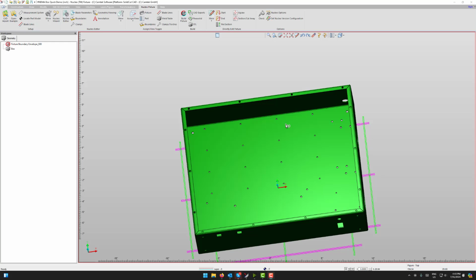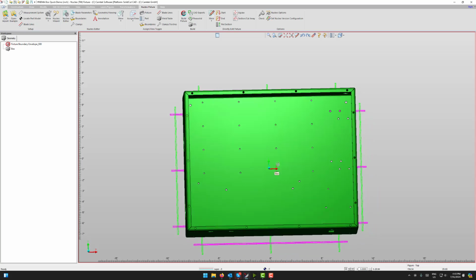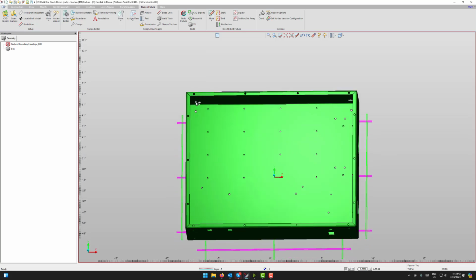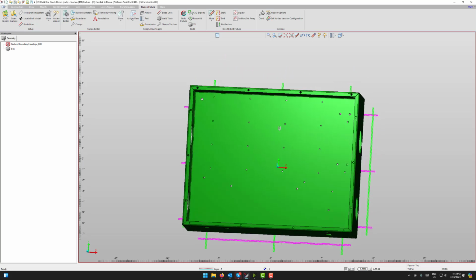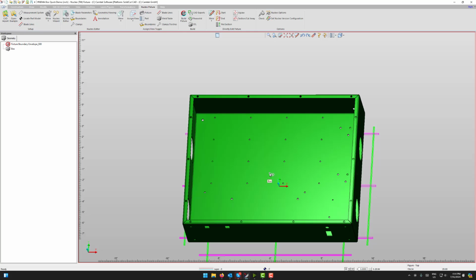Another very useful trick to have in your back pocket is the ability to reference things on a solid, or reference other points to create a point. I'll show you what I mean. Let's just say I want to move this box, and let's say this box had no bottom to it. Typically if I wanted to move this box, I could just tell it to translate, select the midpoint of that bottom face, and I'd be moving by the center of that box. But let's just say this was clear cut all the way through, a completely open box. There was no bottom plate that you could easily select the midpoint of. How would I select the center of this box in that scenario?